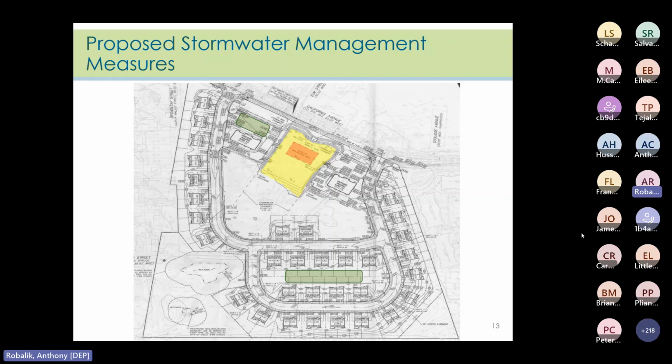So in this case, if this site was being designed under the current rule, an option might be to incorporate into the design multiple small-scale infiltration basins or small-scale bioretention basins, each with contributory drainage areas equal to or less than 2.5 acres. And the areas here highlighted in green just might have been an option for some of the locations of some of those small-scale BMPs.